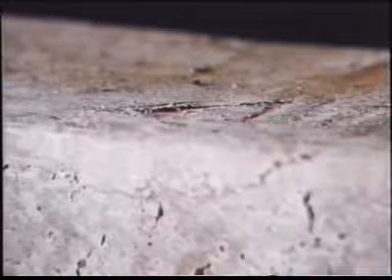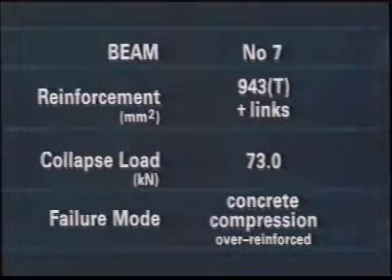It reminds us that if we wish to raise the capacity of the beam to carry more load and bending moment, steel should be incorporated into the compressive zone of the concrete.